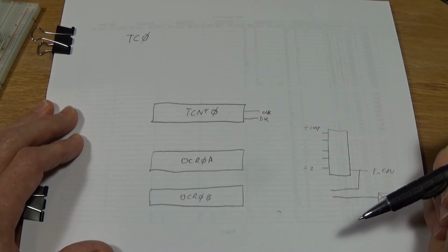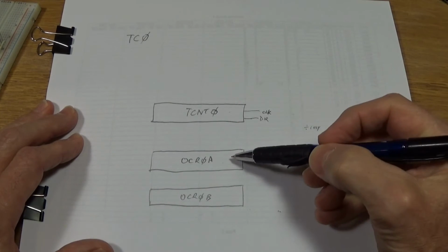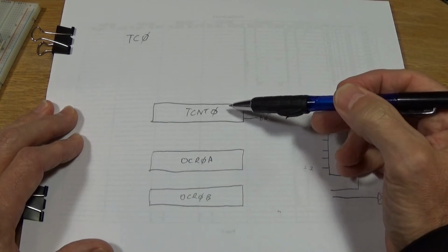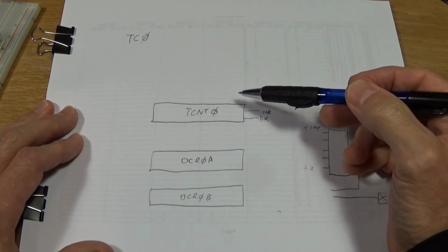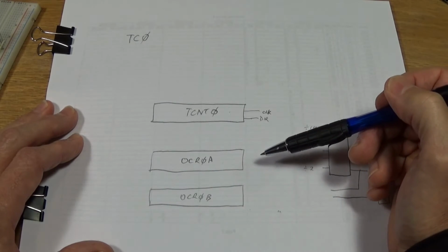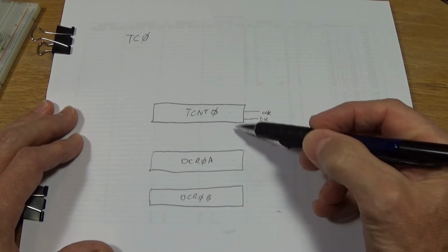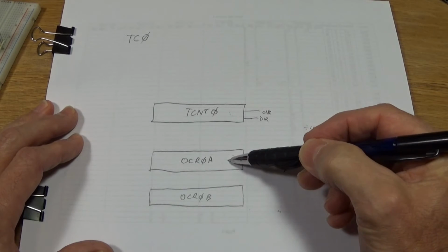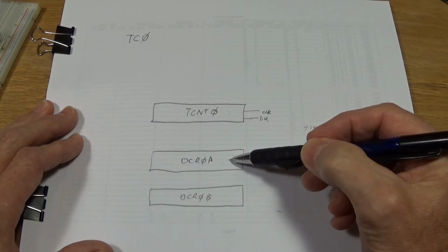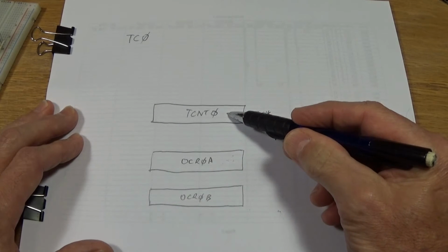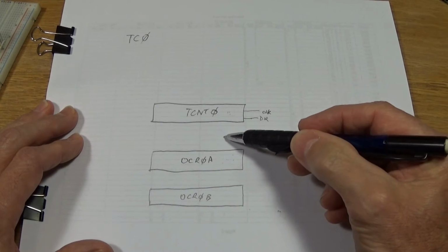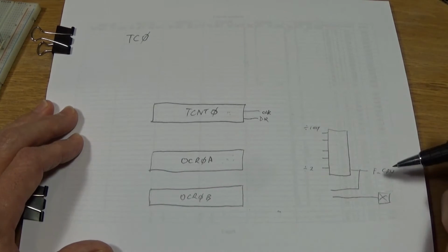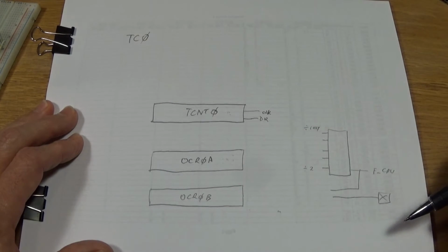And what I'm going to do to make the timer work is I'm going to use this register and this register here. I'm going to tell the timer counter register to just keep incrementing, and every time it reaches 0 it's going to start again, and it just keeps incrementing. And then I'm going to put a fixed value into this register, and then these two will get compared, and when the timer counter register matches this register, the interrupt will be generated, and this register gets reset to 0. And so it's only going to count from 0 up to the value in this register. And I'll show you why it's important to do it that way, to get the right 10 millisecond delay that I want.